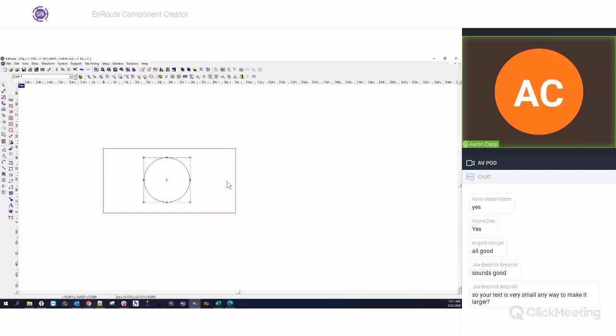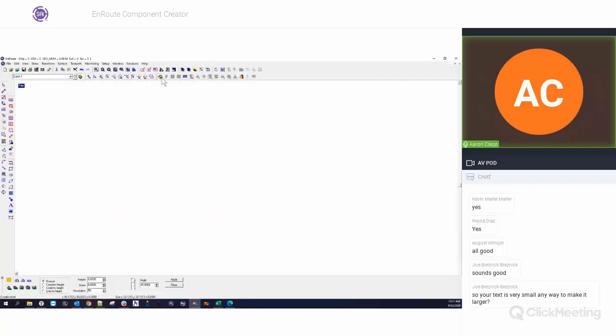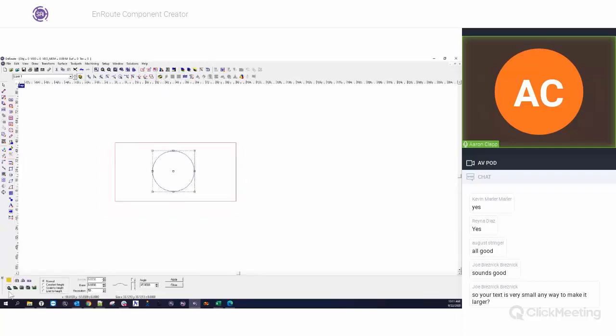So I'm going to go ahead and take my circle here, and I'm going to add a relief to it. I'm going to say add relief, round relief, and let's do a scale to height, and let's do 5 inches since that's the depth that we were using by default. We'll do 5 inches and apply.